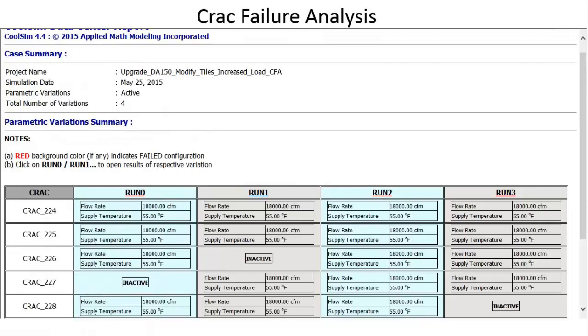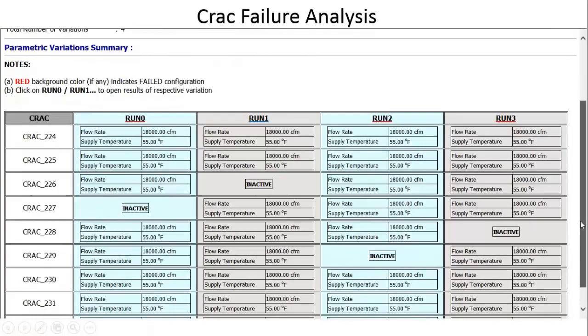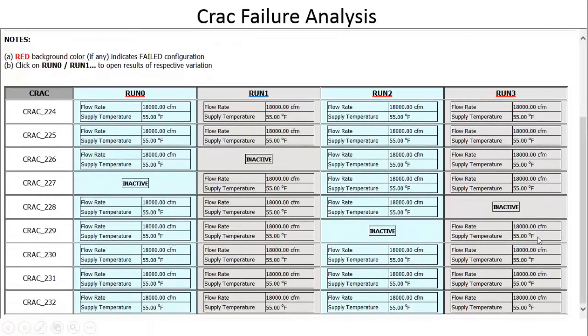So what I did is I assumed, just for purposes of discussion, that we kept the supply temp and the flow rates constant, which we would need in this case because we're already going to be starving a little bit for air because we're right on the edge of having enough air to begin with, and we're about to drop out 18,000 CFM. But let's see what happens.